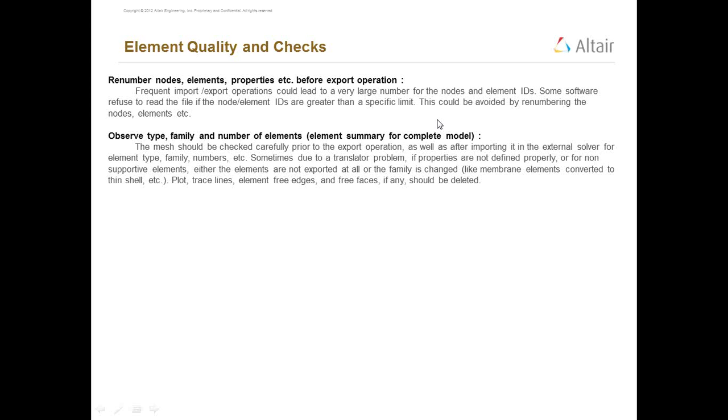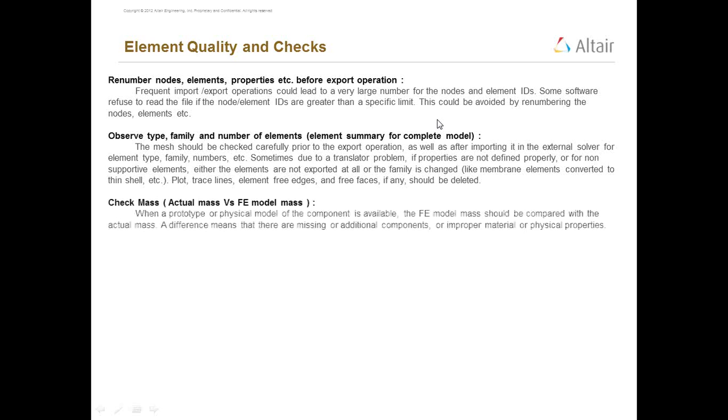Plot, trace line, element free edge or free face, if any, should be deleted. Check mass. Actual mass versus FE model mass. When a prototype or physical model of a component is available, the FE model mass should be compared with the actual mass. A difference means that there are missing or additional components or improper material or physical properties.